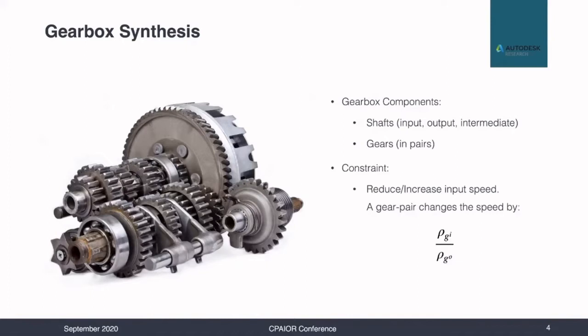Typically, a gearbox is designed to convert the input speed into multiple output speeds according to several transmission ratio values. This is achieved by having multiple shafts and multiple gear pairs connecting the input and the output shafts. When a desired transmission ratio is selected, the necessary gear pairs are engaged by means of clutches.